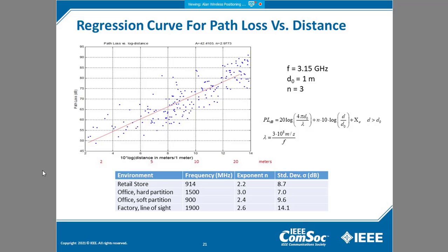First of all, if there is a drift, as time goes on, the difference between the transmitter clock and the receiver clock will go up. If the difference between the transmitter clock and the receiver clock is, for example, 3.3 nanoseconds, then the distance can be determined within an accuracy of around 1 meter.